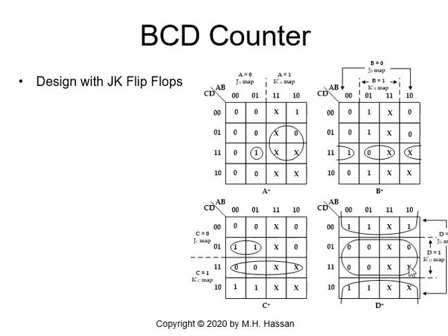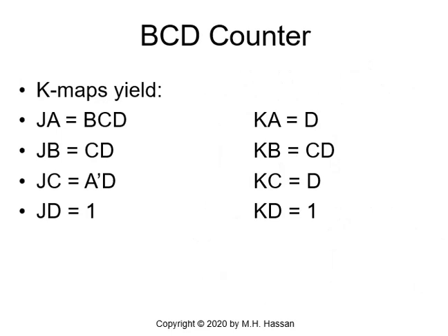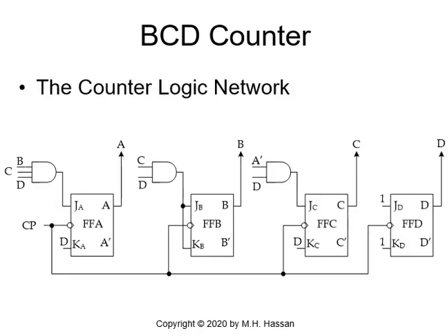The center 2 rows will be D equals 1. So I have to group the zeros to give me KD. And grouping the 0 again will give me only 1. So this will end up with JD equals KD equals 1. See, the shortcut method is so simple, so easy, straightforward. So we found the answer.